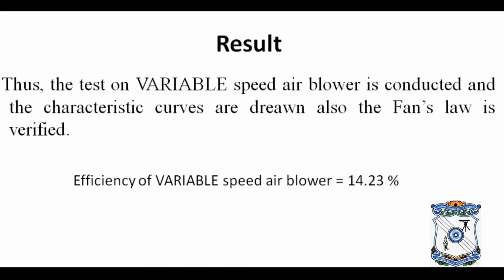The test on this variable speed air blower is conducted, the characteristic curves are drawn, and the Fan's law is verified. The static efficiency, here efficiency refers to static efficiency of the variable speed air blower, is given as 14.23%. With this, the experiment on the variable speed air blower comes to an end.